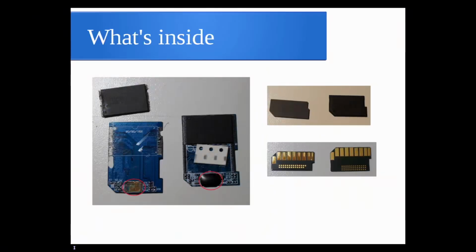This is what's on the inside. So there are generally a couple of broad categories of SD card construction we found. On the left is what we call a discrete construction. They have a standard TSOP flash memory that's soldered onto the board. We show it removed on the left, and the little spot where you see the red circle is where the microcontroller is, a chip on board with a glob of epoxy on top. If you knock off the epoxy, you can see the chip beneath it.